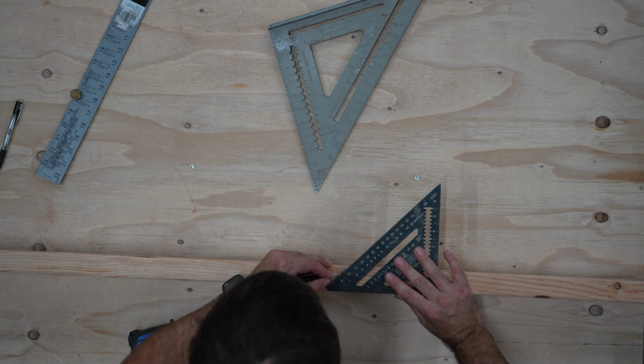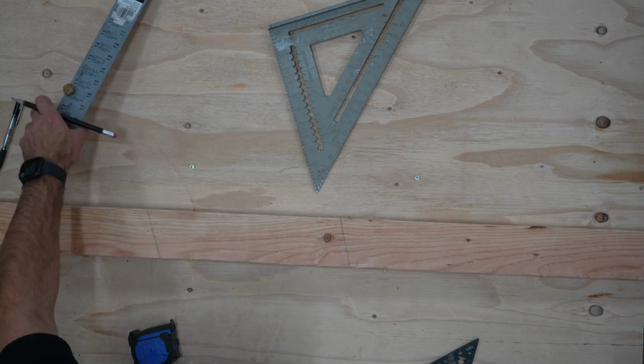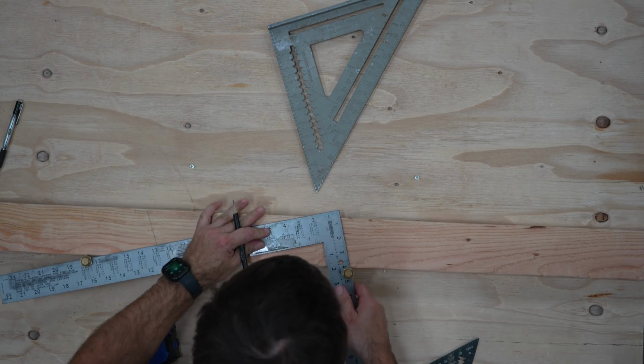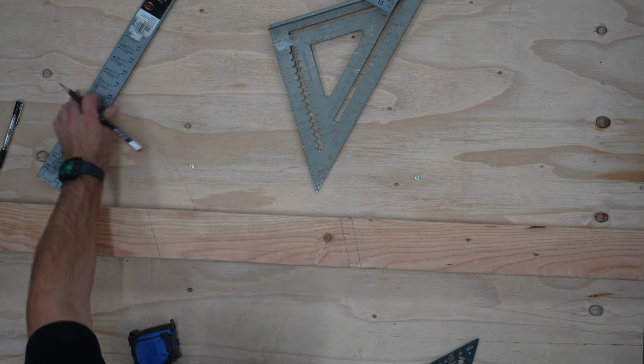because on the ends they need to make a mark on both sides, and one side is done correctly and the other side is done opposite, because once they flip the board over, they forget to also put the framing square on the other side.